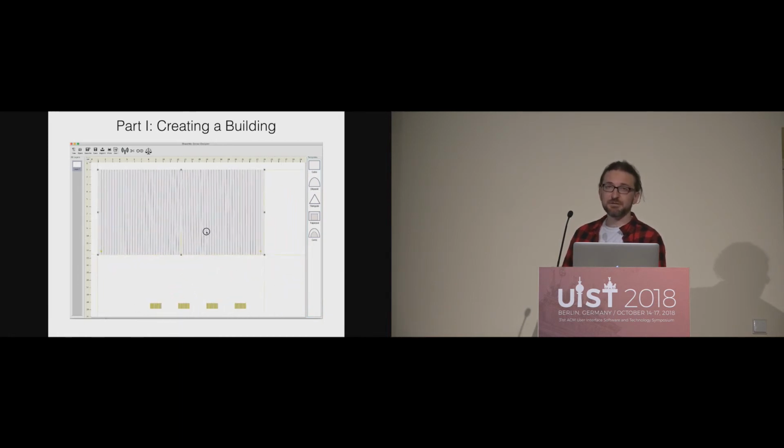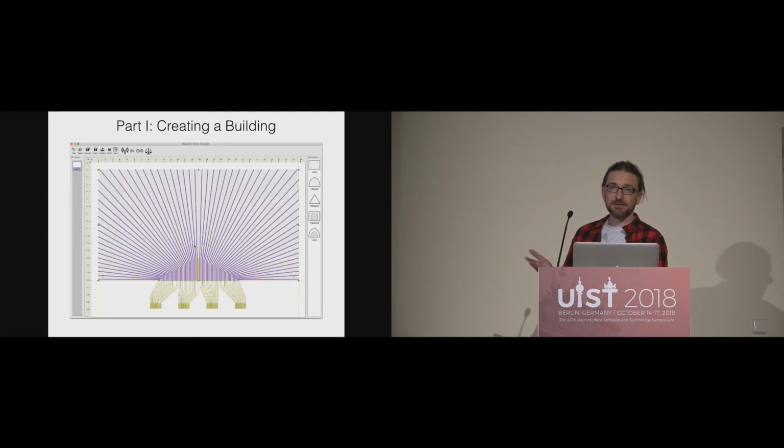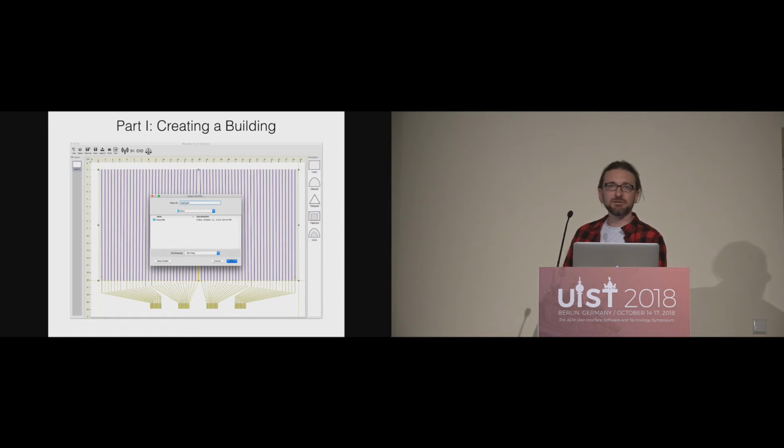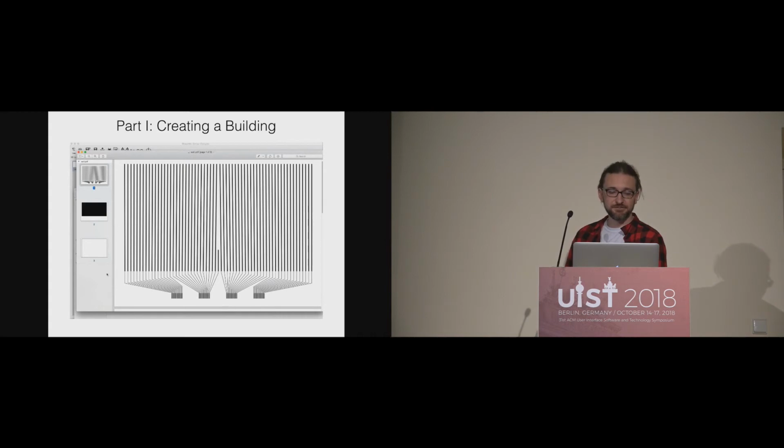The toolkit automatically creates all the sensor topologies that she wants. She can customize the shape and the size of the entire sheet. It creates the wiring to the connections. You can select a topology from those that we have. And finally, these can be exported into a PDF file that can then be sent to the inkjet printer for the silver inkjet printing, and to the laser cutter to cut out the particular sheet.